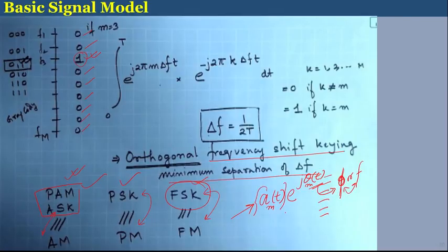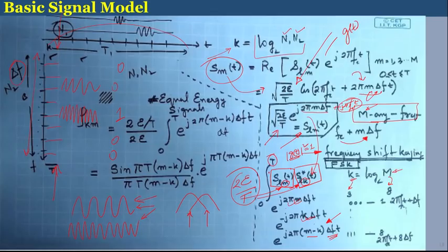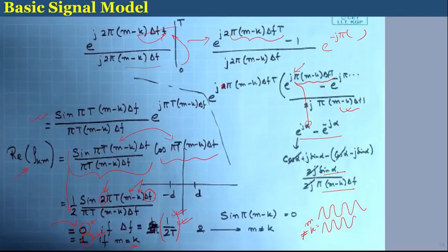signal. Again, since I have used the word basis, we can also go back and see that all these different frequencies that we have used over here can be thought of as basis functions, and they are orthogonal to each other. So, these are orthogonal basis. Now, since they form the orthogonal basis, instead of just selecting them because they are orthogonal, we can actually use them to send data, and we have n number of orthogonal basis functions. So, we can actually use n dimensional signaling, and not only that, we can go beyond that.